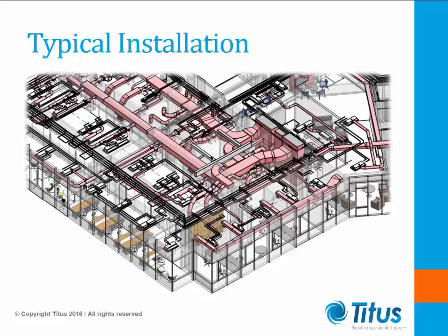When you look at a building overall between a chill beam system and an all air system, you're going to have a similar number of thermostats and a similar number of control loops. And really most times in a well-designed chill beam system, because of some of the inherent benefits, you're going to typically have a lower number of thermostats, a lower number of control loops, and a lower number of zones.